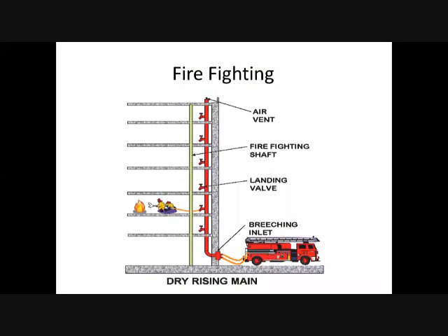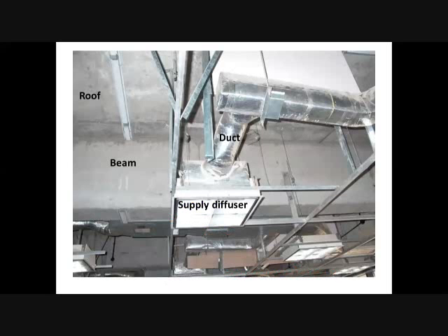Another question, sorry. If you have exposed ceilings, do we need to draw the ducts in the ceiling plan? Of course, if you have an exposed ceiling, then you will have to draw them, because you will design how these ducts will be constructed, because it's part of your design. So you will need to show how the ducts will be, because they have an impact on your interior. If there is a full ceiling, no problem, because they will all be covered, so we'll leave that to the mechanical engineer and the contractor. But if you want them to be exposed, then you have to make sure that they look the way you want them.